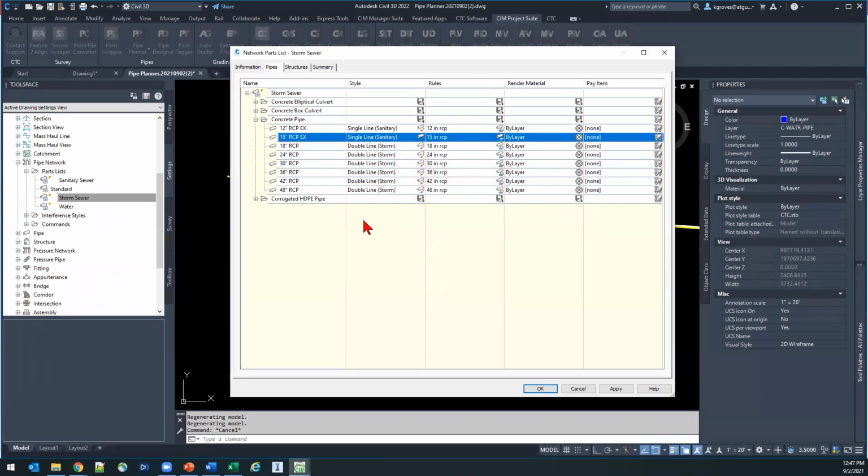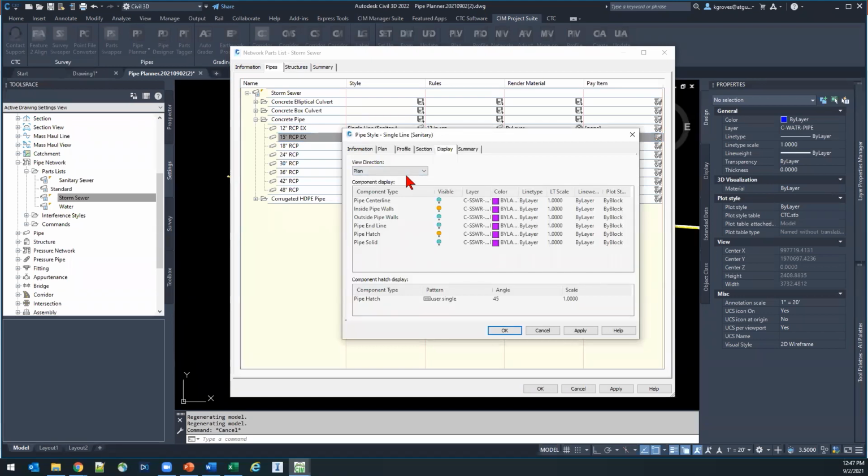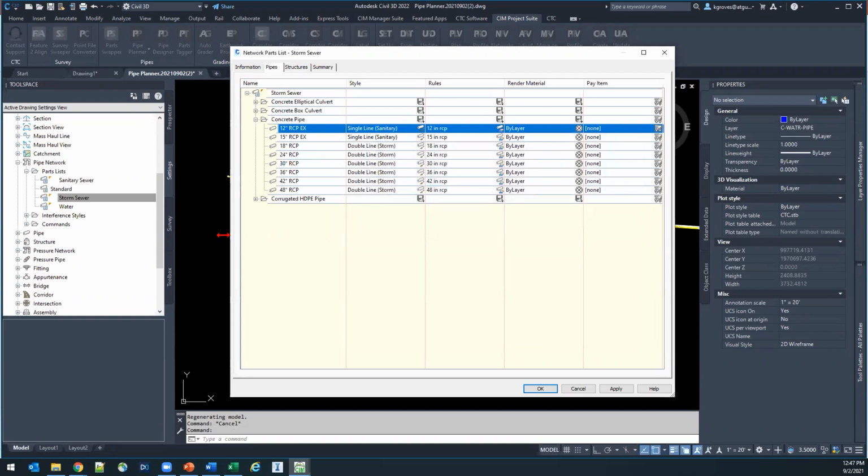For styles, normally I like using layer 0 for a lot of stuff. Unless you want to do something kind of goofy, you're going to be using hard-coded layers for your pipe and pressure network objects. So you're going to need that layer for your proposed sanitary anyway versus your existing sanitary. So all that stuff's going to want to be put together like that. Labels too might be beneficial to have an existing style versus a proposed style. The only reason you need different sanitary versus storm is if you're trying to do different data for it, or if you wanted the different layer control.